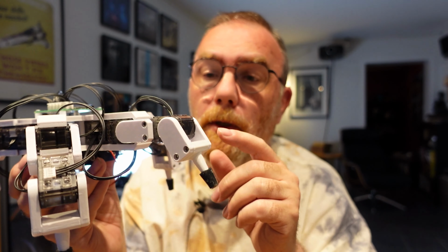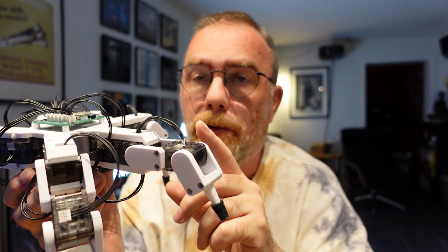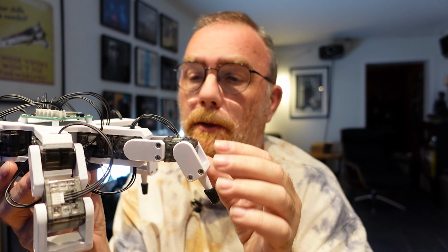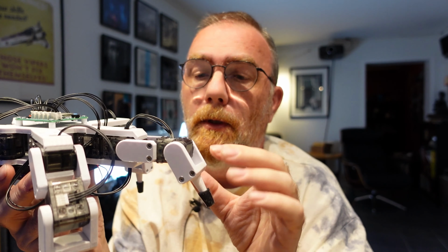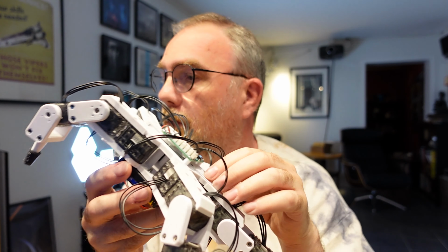So what's next? I still have bugs in the system and I need to iron those out. I'm also going to try to do some PID tuning of the servos. From the factory, these only come with a proportional parameter set, and that makes a difference. If you're running the servo without a load or not installed in the framework, it will behave differently than when it's installed in the robot. So I'll try to do some tuning and see if that makes a difference.